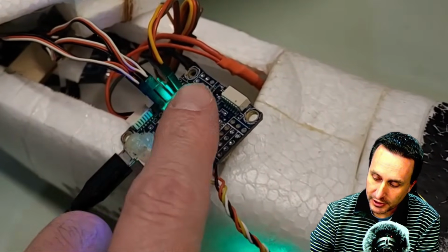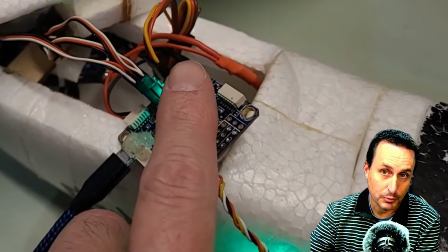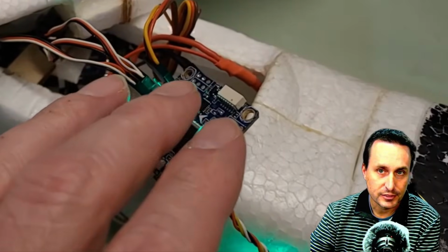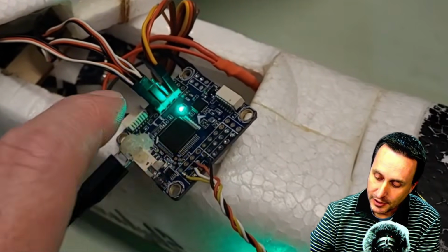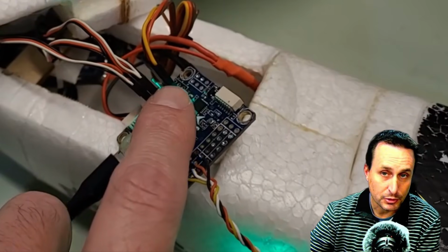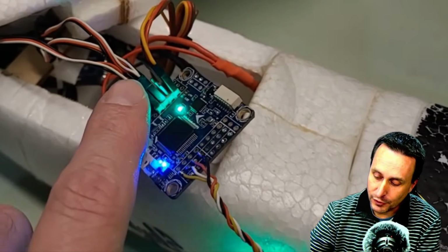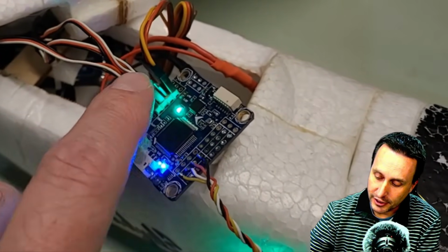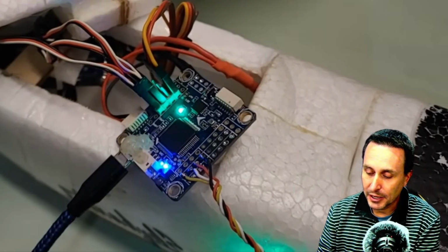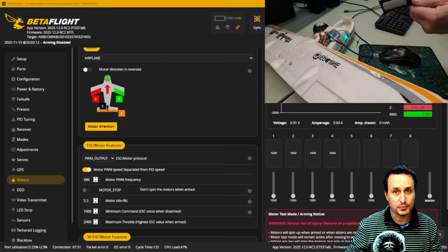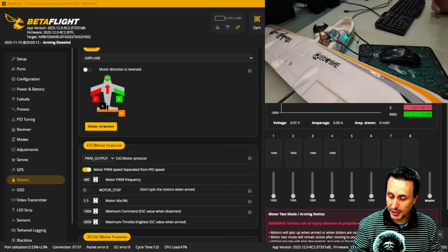Then I have my ailerons plugged in, so that's in motor 1 or PWM1, the motor 1 output on the flight controller. They call it PWM1 as well here on this Omnibus F4 SD card. Then in PWM2 or motor output 2, I've got nothing. And then in 3, I have the ailerons, and in 4, I have the elevator. So elevator, ailerons, nothing, and then the BEC, the motor output for the motor in the back. The other thing you're going to need obviously here too is a battery, to check that your motor's working and have your ESCs or your servos move, you need a battery to power that.